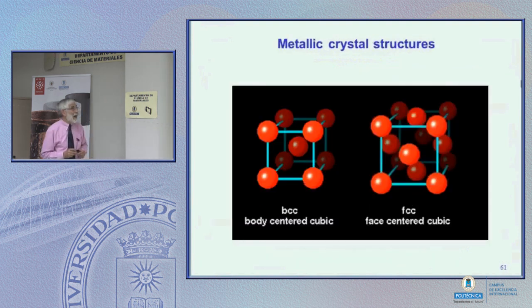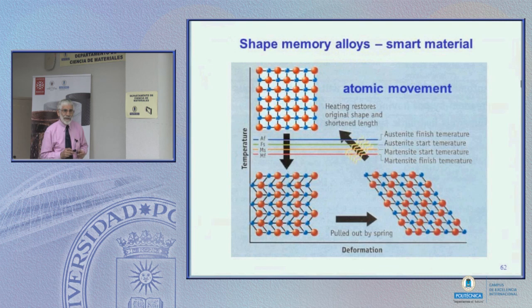So health again. And finally, we know about metal structures. I mentioned them earlier. We know, again, from martensitic transformations, transformations which are not dependent on diffusion, the movement of atoms, but which are dependent on a lattice structure suddenly changing shape, normally because we drop the temperature. So we take this structure, and as we drop the temperature, all the atoms, ions, stay in the same neighbors, but it changes its type of structure, and it looks, therefore, slightly different. When we pull this, we can straighten this out, and then when we heat it again, it goes back to this structure. So notice it's this shape. Now we pull it, change its shape, but by heating it, it goes back to its structure, and then by cooling it, it comes back to the same shape.